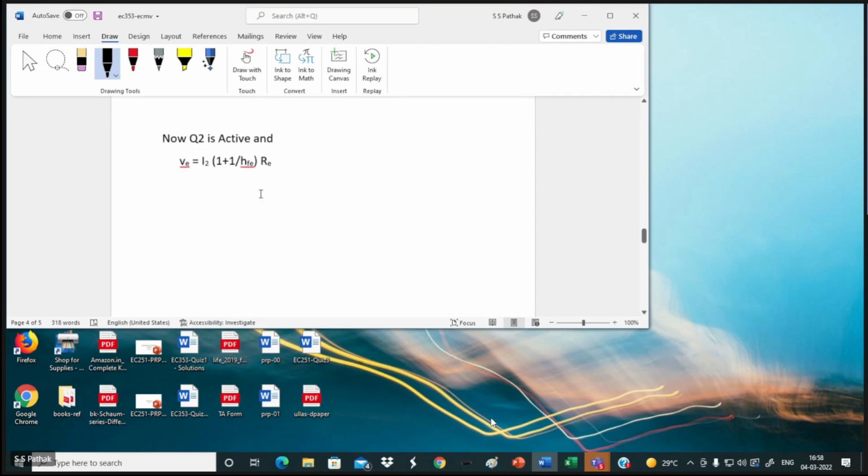So here T is 0.69 (R plus RC1) into C. So this is the width of the pulse. So RC2 is not coming in the calculation anywhere except for the biasing, but RC2 is independent of the value of RC1. I think that is the beauty of this emitter coupled multivibrator.